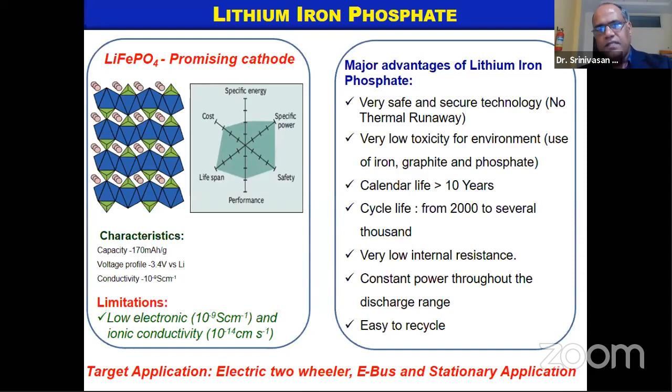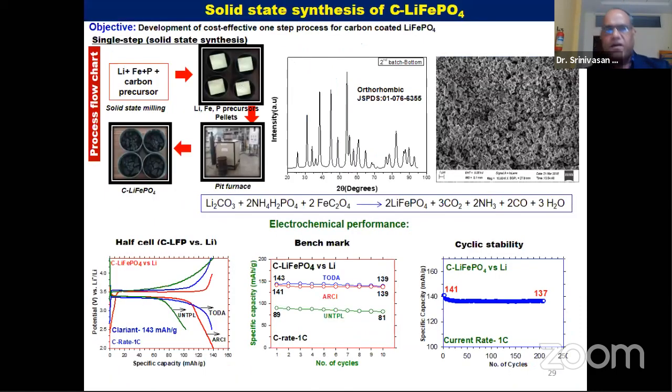For that, this is the limitation because it has low electronic and ionic conductivity. What we have done is synthesize an in situ carbon-coated LiFePO4 through a solid state process. We have taken lithium carbonate as the lithium precursor, ammonium dihydrogen orthophosphate as the phosphorus precursor, and iron oxalate as the iron precursor.